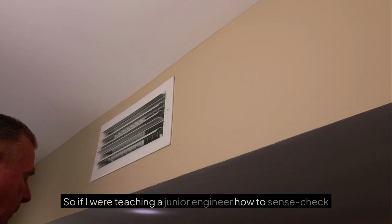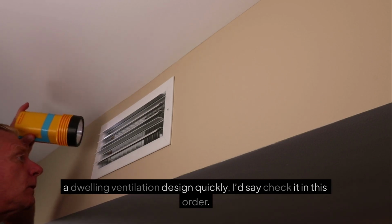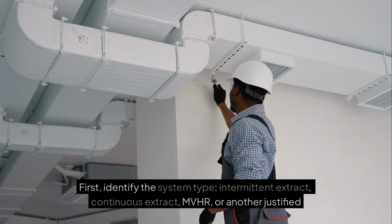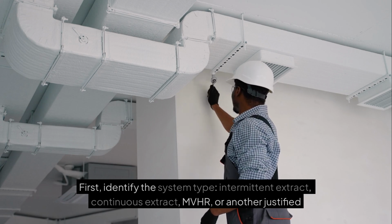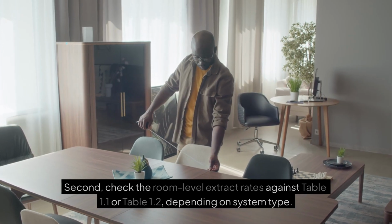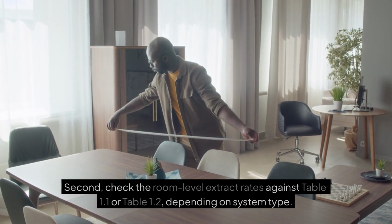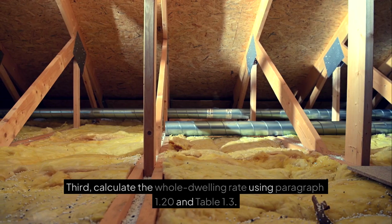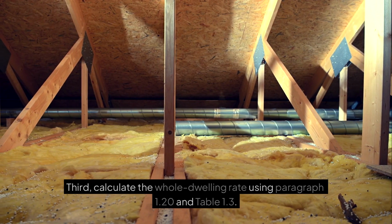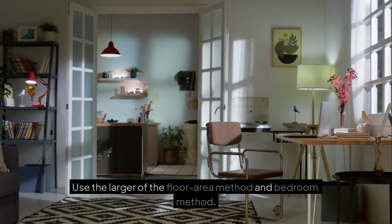So if I were teaching a junior engineer how to sense check a dwelling ventilation design quickly, I'd say check it in this order. First, identify the system type: intermittent extract, continuous extract, MVHR, or another justified performance-based route. Second, check the room-level extract rates against Table 1.1 or Table 1.2, depending on system type. Third, calculate the whole dwelling rate using paragraph 1.20 and Table 1.3. Use the larger of the floor area method and bedroom method.